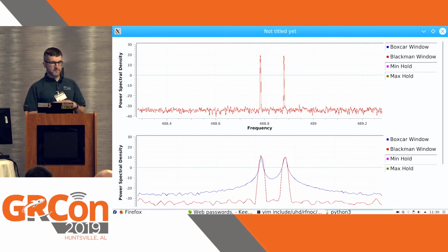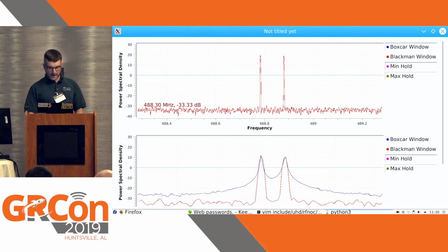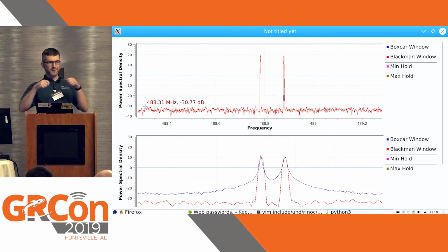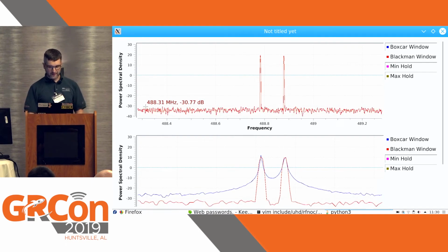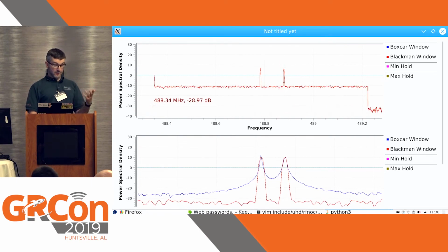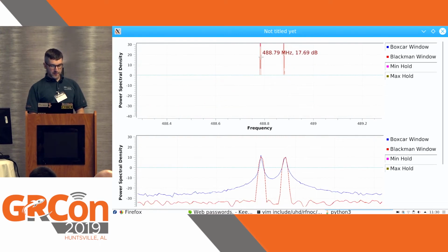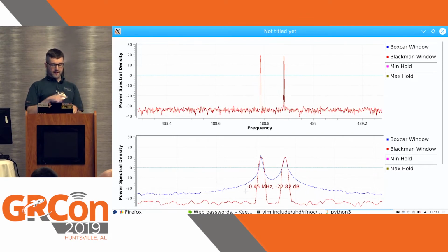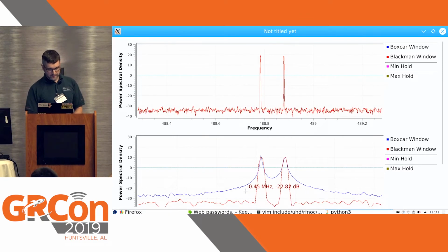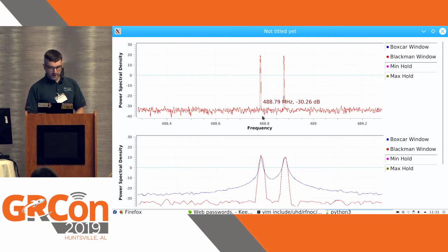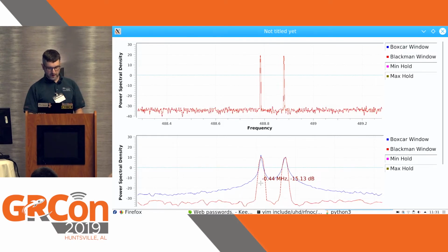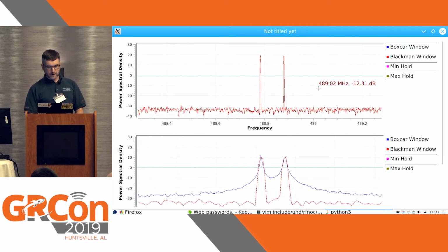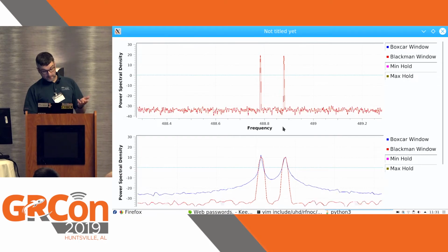But the noise will always spread out over all the bins. So I have more bins in the top, so I have to divide the energy over more bins, so it'll go down a bit. Another way to look at it is, this here is a pretty sharp line, whereas here it's not. If you think of it as integrating over the frequency domain, I'm basically putting some of the energy in the width, where here it's higher, okay? So that's one part of it.